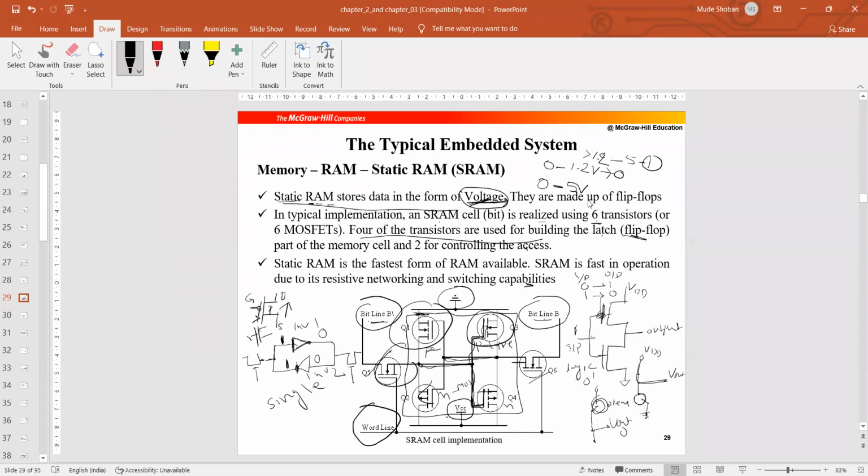So here you could notice one thing, the cell design. A single chip can be designed like this. For single bit storage, it has bit line and complement lines for reading, but 6 transistors are used. No capacitors are there inside these. 4 transistors form the flip-flop for storing bits, and 2 are for accessing the data. Because accessing means, for the reading purpose and for the writing purpose, you have to collect it from some other place.